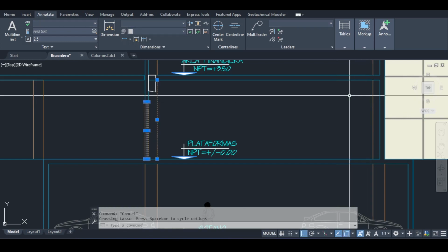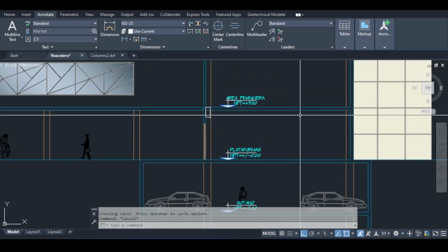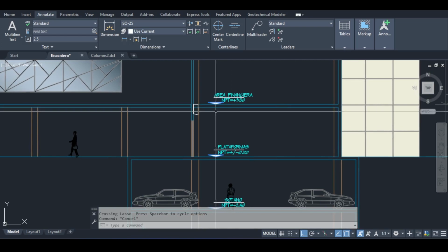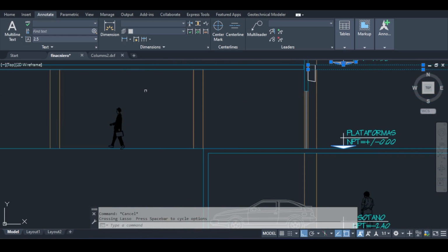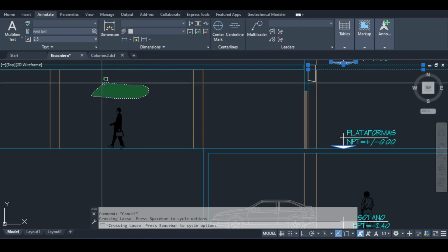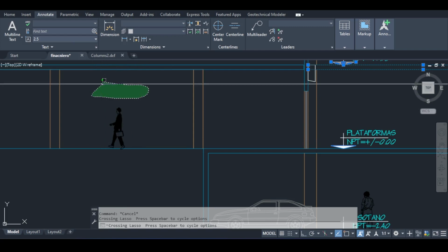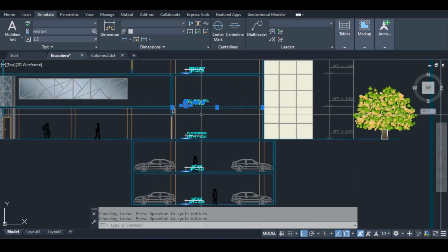So now I will not be doing this in this series so far because I don't see a reason to do that so far. I'm assuming that there is nothing like that here. But I want to keep this in mind. I want to just remind you that, hey, there is a height that you need to keep in mind here, and that is the height of the person. And you cannot just put the slab 20 centimeters above the person's head. This will cause all kinds of problems, and the architectural engineer will actually scream in agony when he sees that. So keep that in mind when you assume thicknesses.